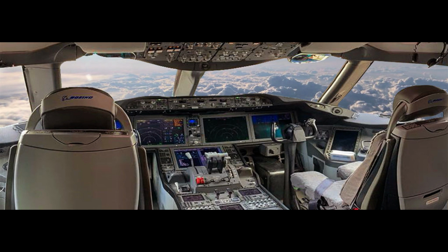3. Minimum altitude. Autopilots are certified for use above a specified minimum altitude above ground level, AGL. Some higher performance and higher service ceiling aircraft require autopilot control above certain airspeeds and altitudes. The flight manual and operations manual, if any, should be consulted to ensure that the pilot does not operate the aircraft outside specified limits.